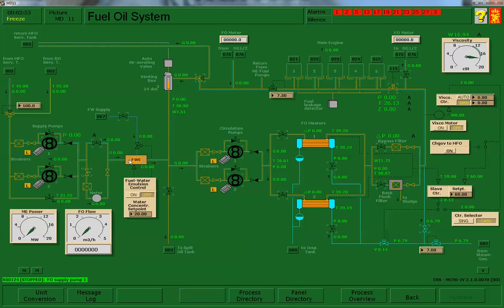This is actually an emulsification system that is used if you're trying to lower NOx. It's by way of putting water into the fuel, to cool down the combustion process and produce less oxides of nitrogen. And then it goes through a circulation pump, through the fuel oil heater. This is a back flushing filter. This is the type that has candles, and when one of the strainers gets dirty, it automatically switches to a new one.